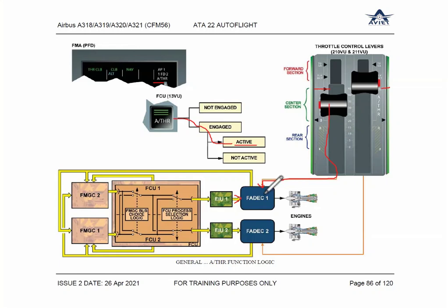So does this lever have some importance in auto thrust condition? What is the importance? When auto thrust disconnects, the system will take this lever position for the thrust.